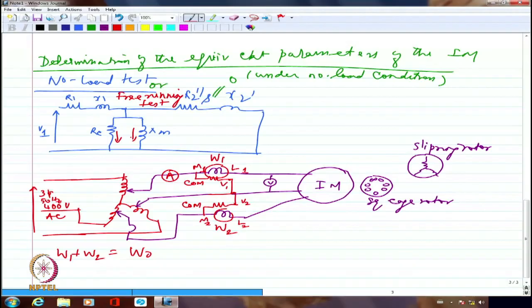If I just reverse, the 180 degree phase shift, 30 plus 5 or 30 minus 5, comes out to be maybe 180 minus something, because of which you will automatically see that the reading becomes positive. So you would not have this difficulty if we reverse the current coil.